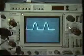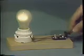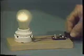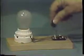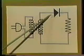The diode conducts, or current flows, during the positive half cycle. In other words, the diode acts like a closed switch. During the negative half cycle, the diode is reverse biased and does not conduct. In other words, it acts like a switch in the open position. This is called a half-wave rectifier.